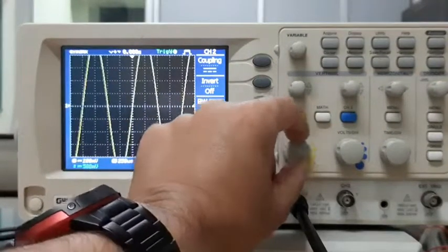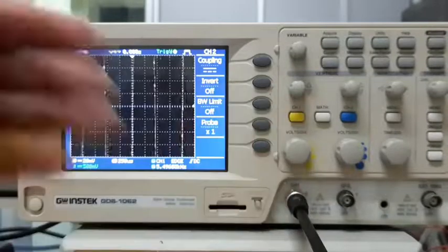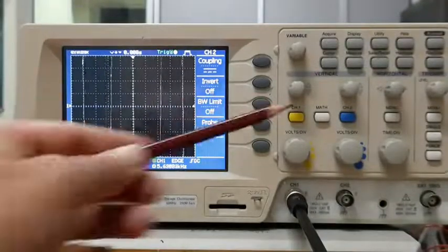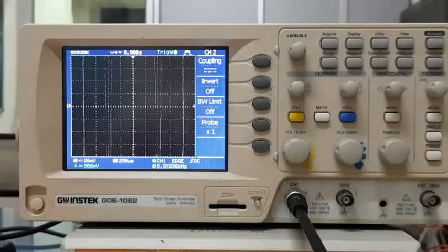So if you know the range, for example, what can happen is, suppose by mistake, your oscilloscope is set in this vertical scale, which is 20 millivolt. That means maximum you can see is about 80 millivolts amplitude signal, whereas the signal you are giving is 1 volt amplitude. And then what you will see is something like this, and then you cannot make sense of it. You will think that I was trying to give a sinusoidal waveform, which should have looked like a sine wave, right? But it shows me something, these vertical lines which are jumping here and there, right? There's nothing wrong with the input signal. In fact, there's nothing wrong with the measurement also from the oscilloscope.